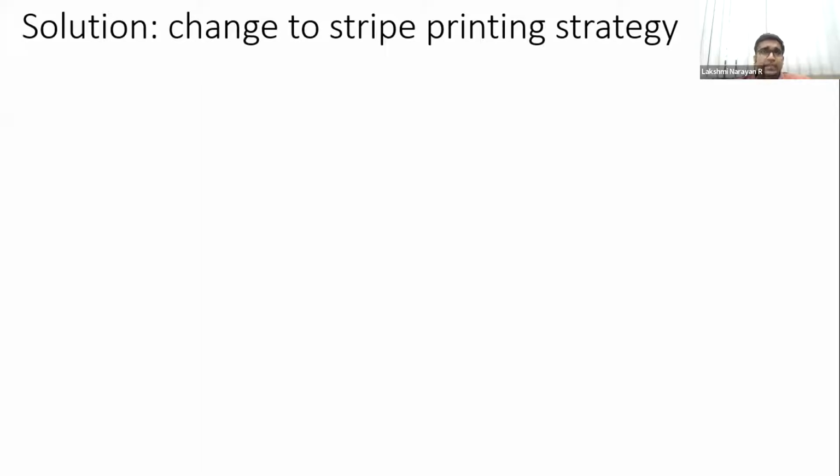Various methods were tried. Some people tried remelting strategies. That is, once you do the bed, once you do the printing, you again run the laser in the same pattern so that the materials are remelted and homogenized. But that did not solve the problem.